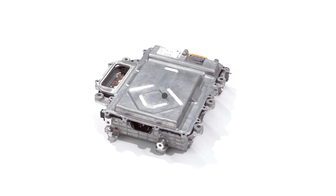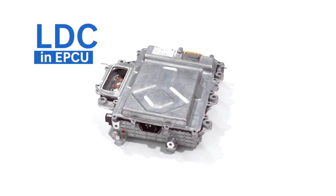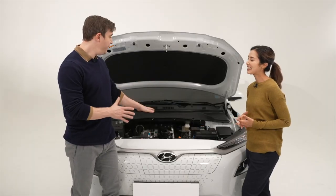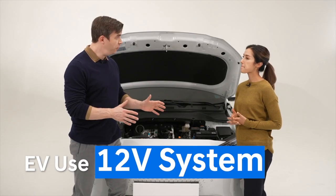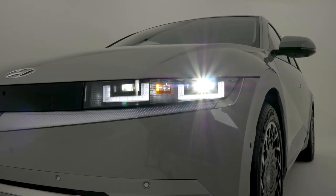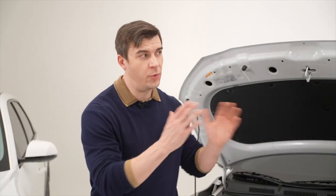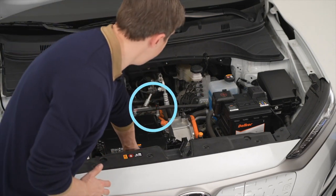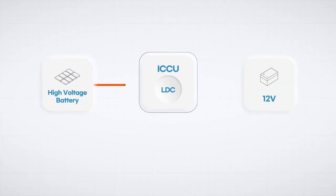An LDC, that stands for low voltage DC-DC converter. Electric vehicles also use 12 volts to do general electric operations. I'm talking things like turning on the headlights or using the windshield wipers. So here is the LDC, it's right under here. The LDC is a converter, and it converts the high voltage of the battery to a lower voltage.